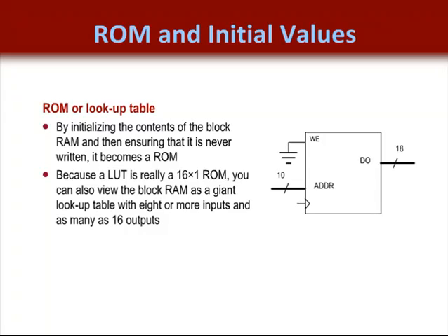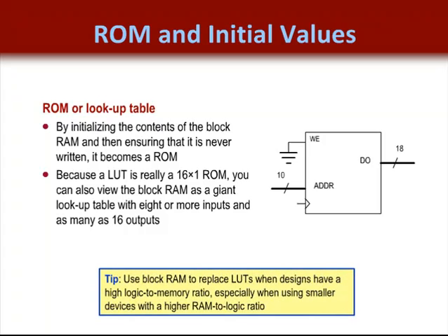To encode block RAMs in this way, remember that all the blocks can have their initial content stored in the configuration bit stream. So upon power-up, every block RAM is programmed. The challenge is writing the initialization string to initialize the 18K bit block RAM. It can get kind of big, and being that it's done in hexadecimal can be a little challenging. So try to use the block RAM for combinatorial logic. It saves a ton of LUTs.